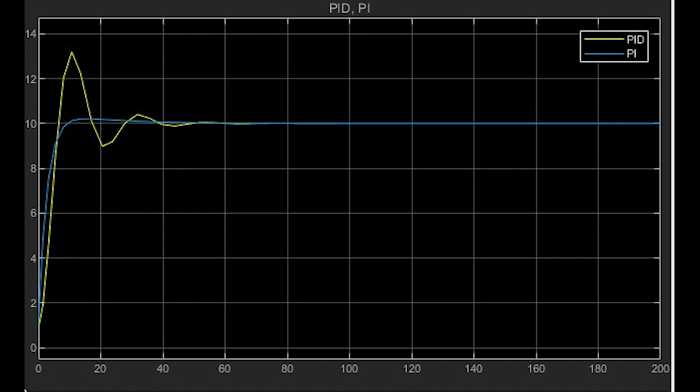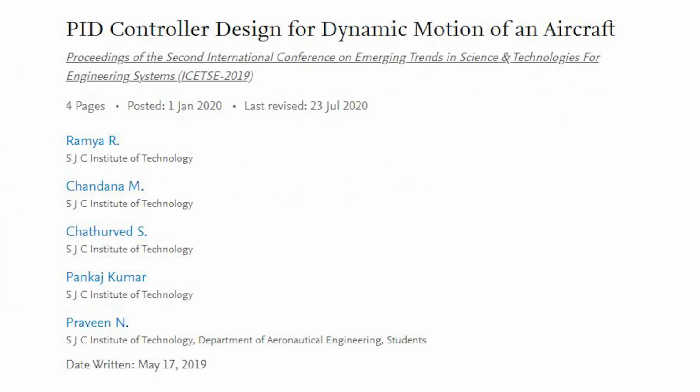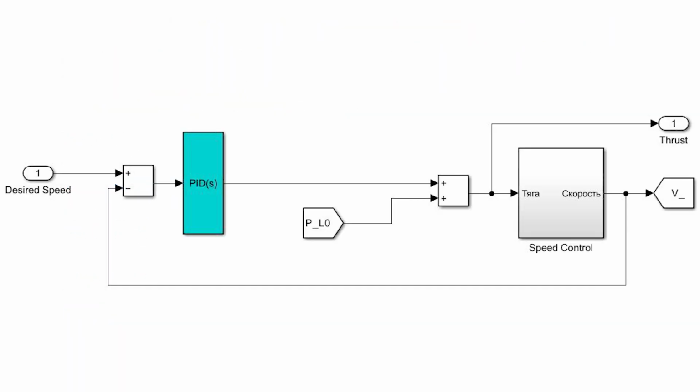one of the main cons of such controllers. You have to find the optimal values of coefficients for them to perform well. Despite this fact, PID controllers are really robust and useful even in flight dynamics. They may be and actually are used to control simple systems in non-complex conditions. For instance, in the task my former flight dynamics teacher and I are solving right now, the PID controller I use to maintain the desired speed of the aircraft.